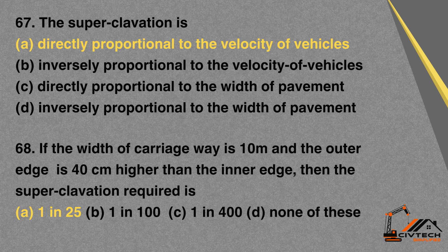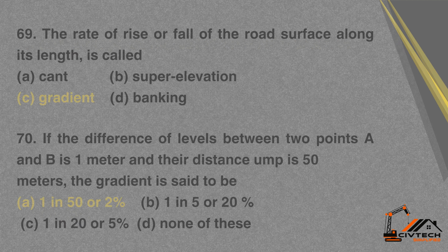68. If the width of carriageway is 10 meters and the outer edge is 40 centimeters higher than the inner edge, then the superelevation required is A. 1 in 25, B. 1 in 100, C. 1 in 400, D. None of these. Correct option, A. 1 in 25.